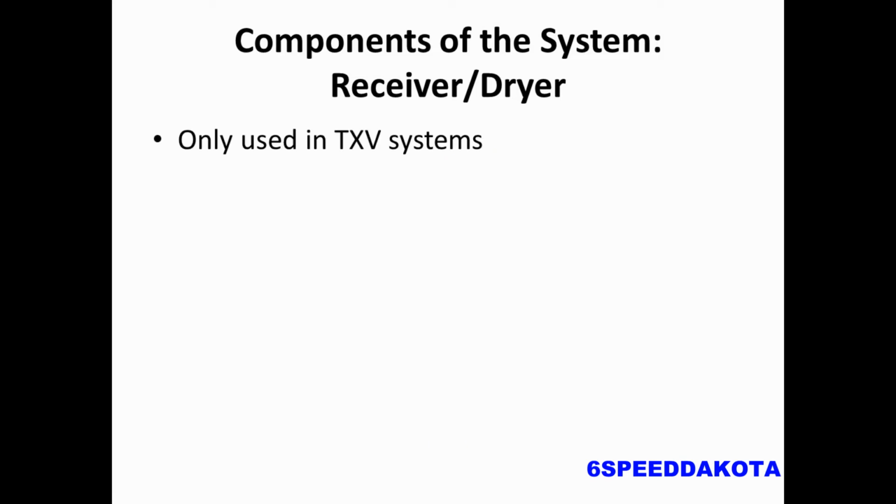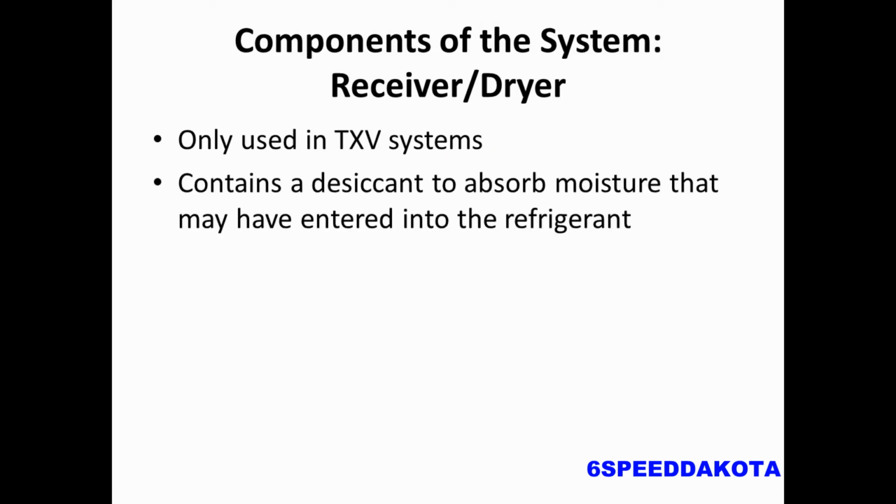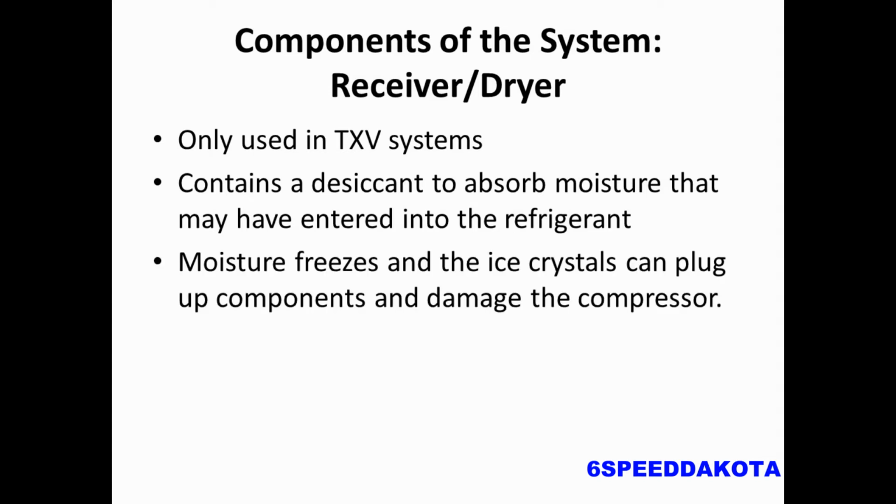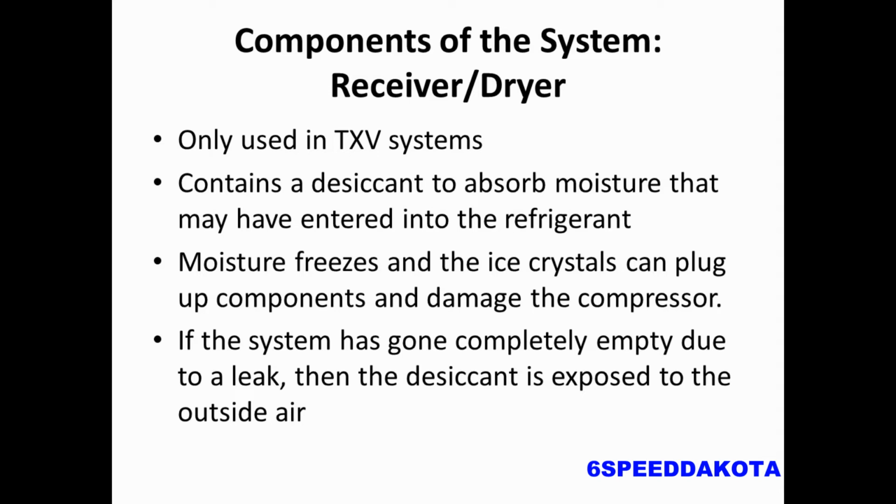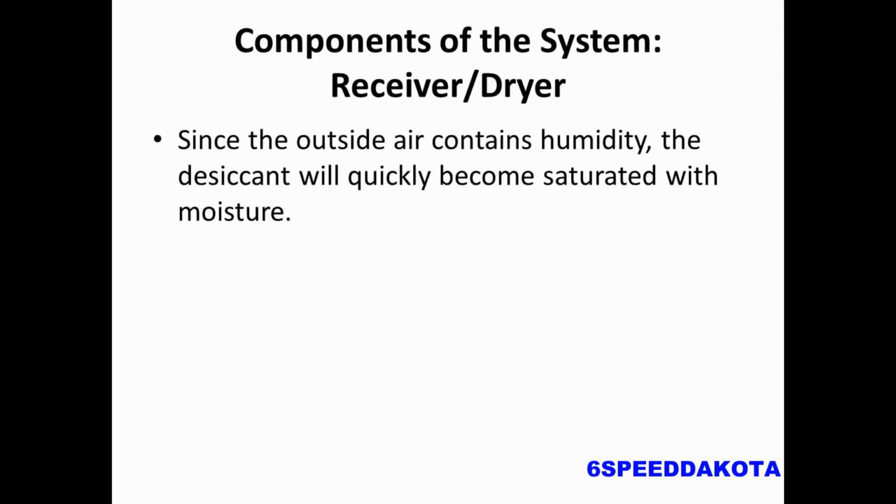It's only used in a TXV system, and it contains a desiccant that absorbs any kind of moisture that may have entered the refrigerant, say if the system wasn't vacuumed down properly. Moisture freezes and ice crystals can actually plug up components and cause damage to the compressor. So if the system has gone completely empty, if the system had a leak in it, what ends up happening is if the leak isn't fixed, the system is now exposed to outside air, and as the outside air rushes in, it can saturate the desiccant.